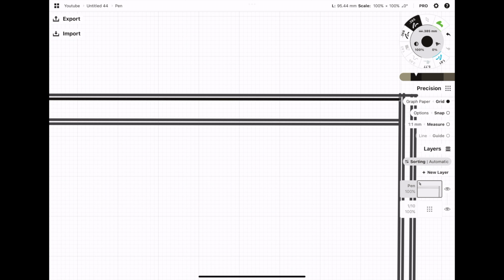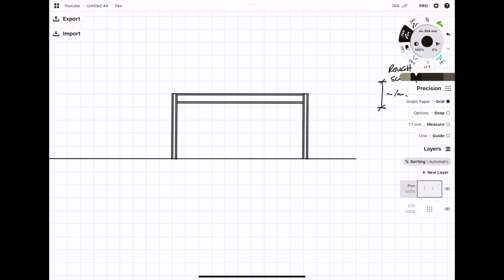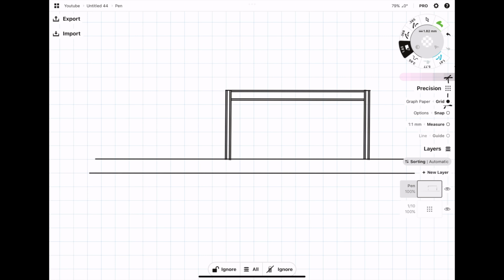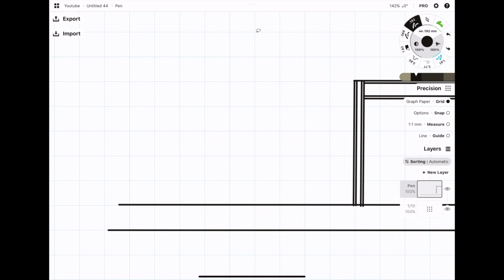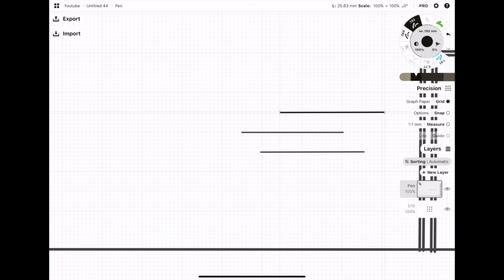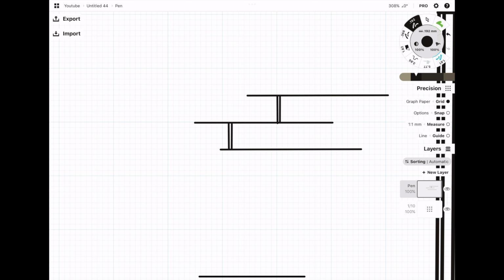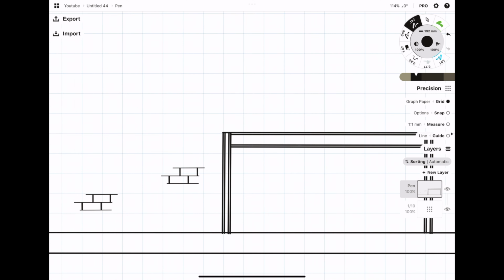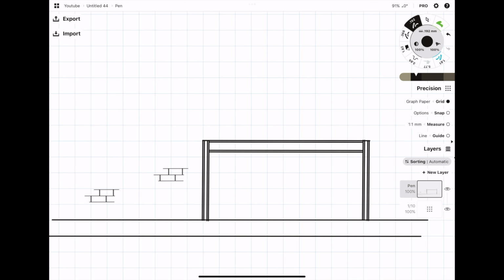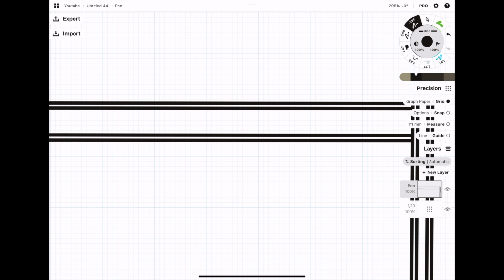When I'm sketching, I try to only draw what I think is going to be necessary to benefit the reader of the sketch. I quite like to show any surrounding structure which might be impacted by the new structure. So in this instance, the walls on either side is going to be important to show. This is just a very quick hatch which I'm doing to show that this is a large panel of masonry. We also have steel beams connecting into this large steel frame. So I think it's going to be quite important that I show this on the sketch.